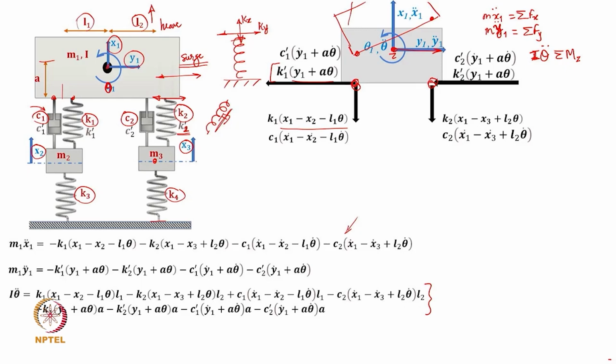Okay. So, the suspension could be like this at certain angle, and then the damping will also be in parallel to it. All of that will generate both horizontal and vertical components of it. Now, these having quantified as k1 and k1 dash, k2 and k2 dash, whenever there is a horizontal y motion that happens, the forces in the horizontal or y direction at the point of connection of the spring or suspension is given by this relationship, which is k1 dash into y1 plus a theta. Because of that tilt motion, this is the net stretch in the spring multiplied by the spring constant gives the force. Similar force will be generated corresponding to the dashpot velocities, and that is how y1 dot plus a theta dot, these are all the forces which will get generated. Okay, the similar force will be generated here.